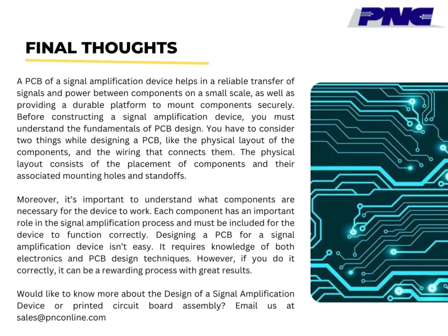Before constructing a signal amplification device, you must understand the fundamentals of PCB design. You have to consider two things while designing a PCB: the physical layout of the components, and the wiring that connects them. The physical layout consists of the placement of components and their associated mounting holes and standoffs. Moreover, it's important to understand what components are necessary for the device to work. Each component has an important role in the signal amplification process and must be included for the device to function